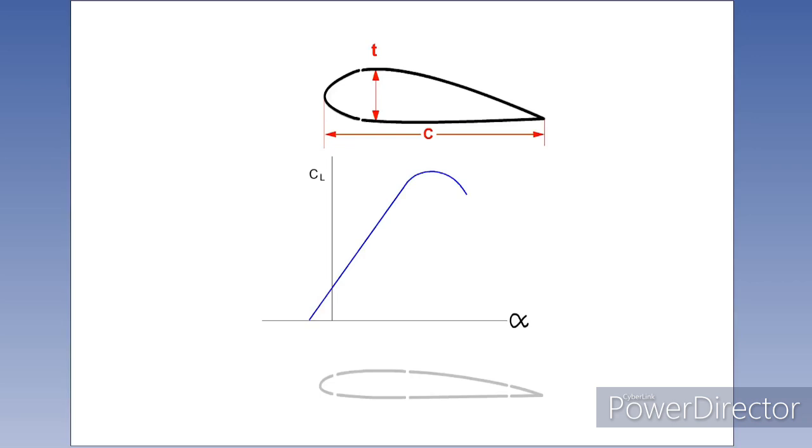These features are more typical of a wing designed for efficient high-speed operation. With a sharper leading edge, a low thickness chord ratio, and an aft maximum thickness and camber, a comparison of the shapes of the two lift curves shows the difference between the profiles' stalling characteristics.